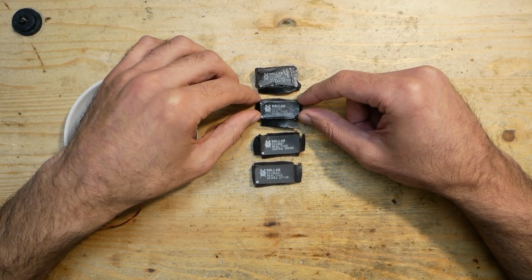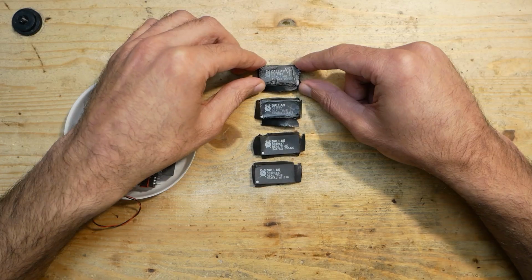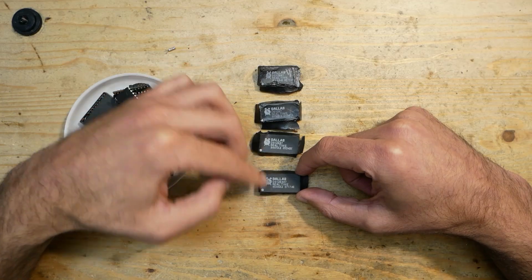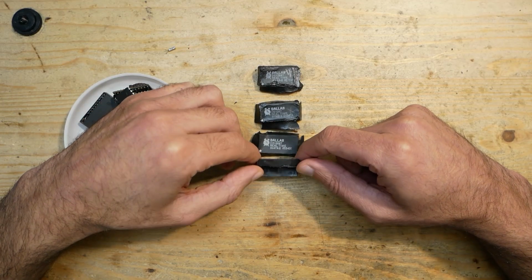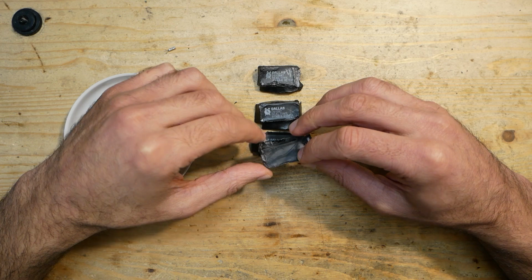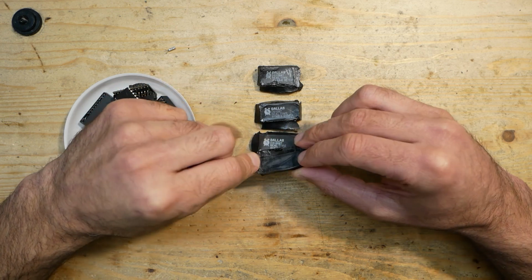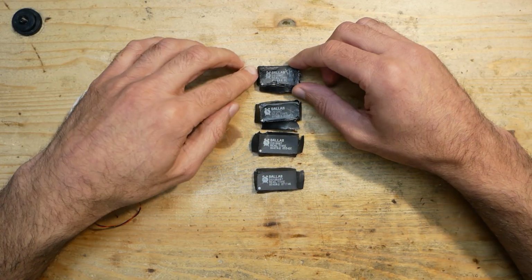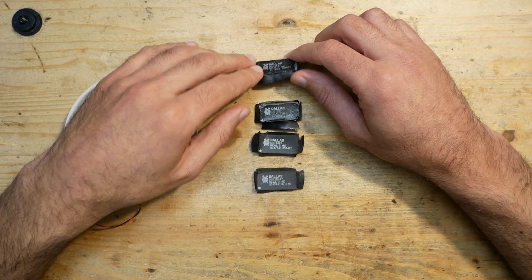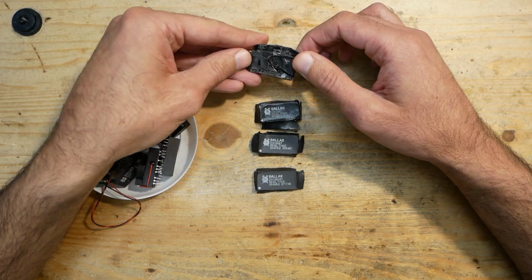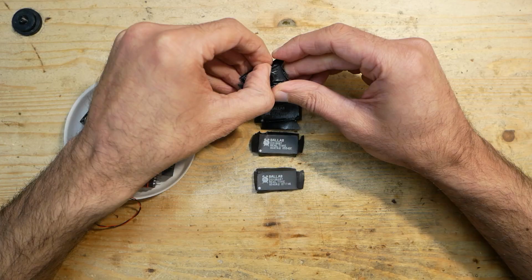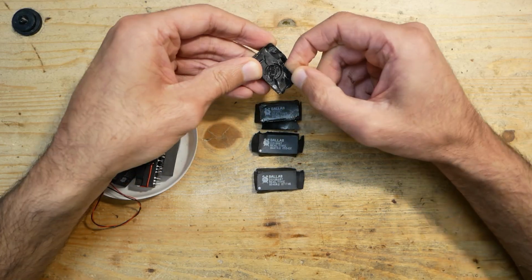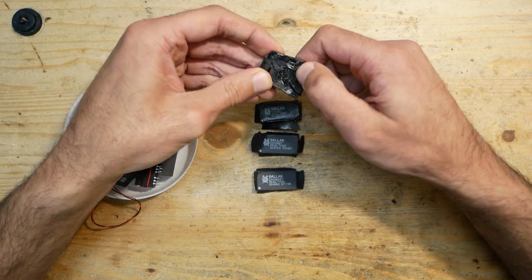As you see, the first part got the most heat. The plastic melted and it was too much. The second one I already didn't heat up as much, and the third and fourth it was less and less heat. I found that the best temperature is maybe around 70 to 80 degrees Celsius. The most heat you would need is to remove the plastic cover, but as soon as it's off, the resin falls apart quite easily. As you see, the leftovers from the first try still have some resin inside. And it is again extremely hard. If I wanted to get it out, I'd need to heat it up once again. Otherwise, it would be hard even to scratch it.